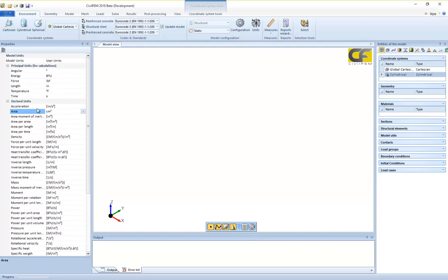And take into account, later we will show you that the units can be inconsistent. That means that here you can define your units in the beginning, but then later you can mix. For example, geometry can be defined by default in inches, but you can change them anytime. And then material properties can be defined in the international system, for instance, and then apply forces using, instead of pounds, newtons or kilonewtons or kilograms.